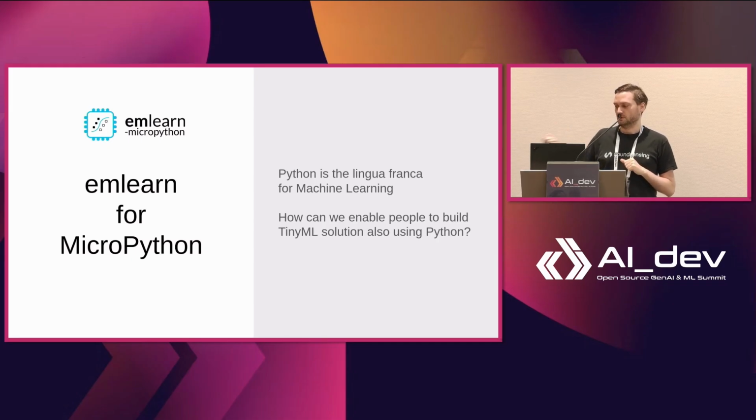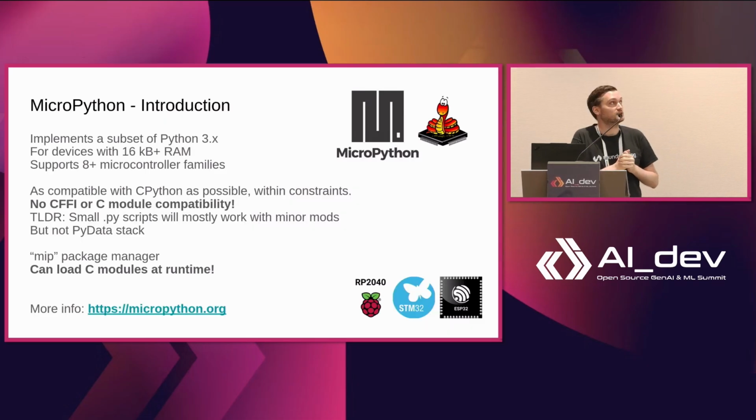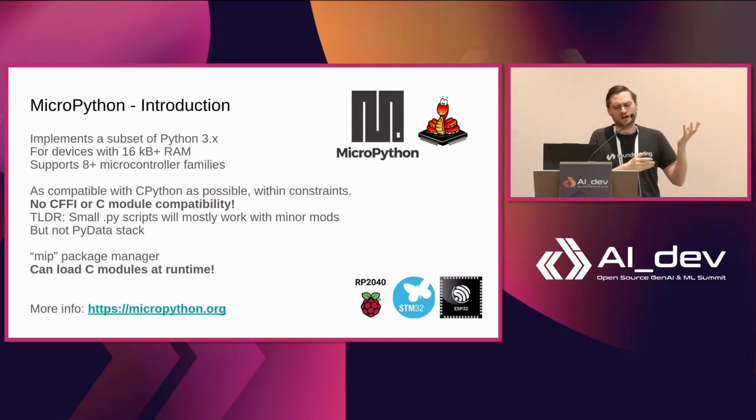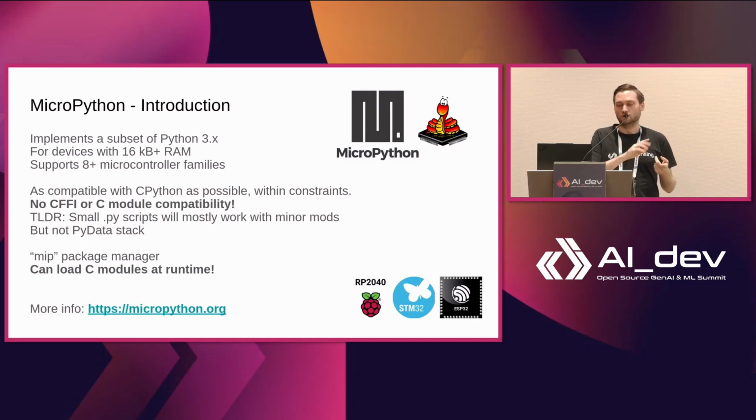So how can we enable people to build this kind of TinyML devices using Python? That's made possible using MicroPython, because it's been available for around 10 years now, so it's getting really nice and mature. And it's as compatible with CPython, like regular Python, as possible. But of course, there are constraints when you have these very, very small devices. For example, the C API is not compatible, so it means you don't get regular NumPy, TensorFlow, etc.